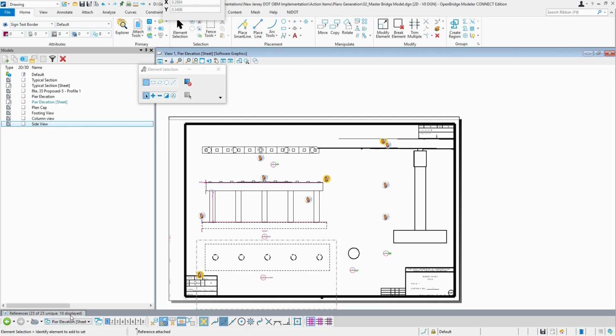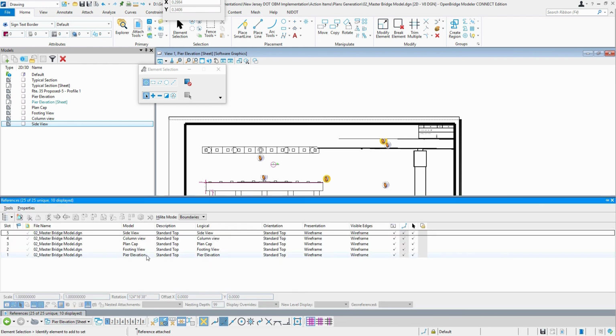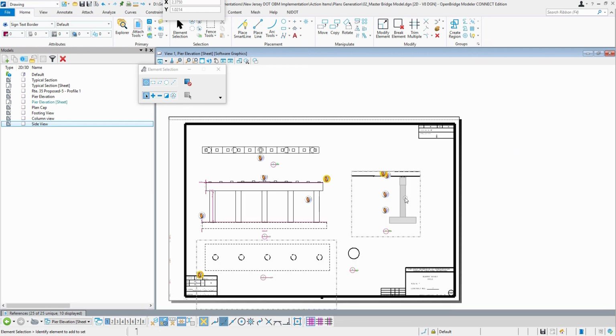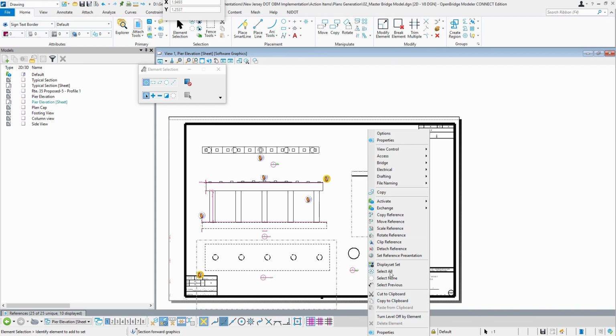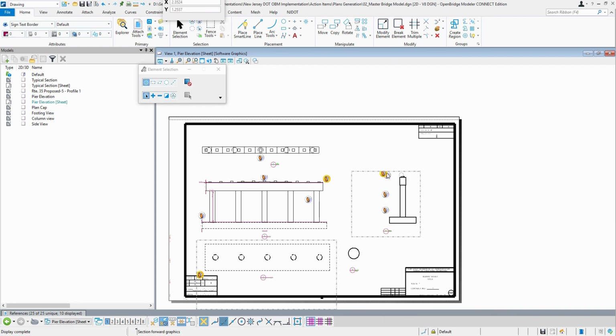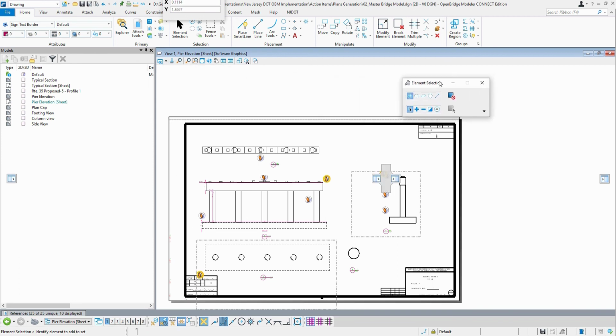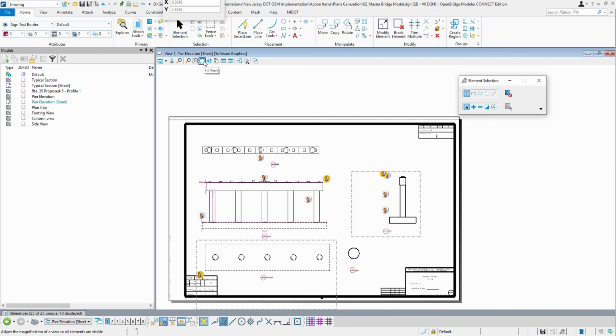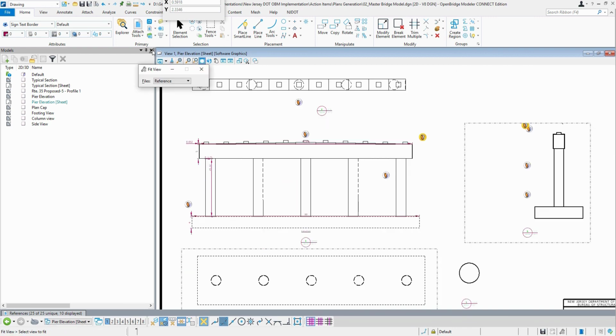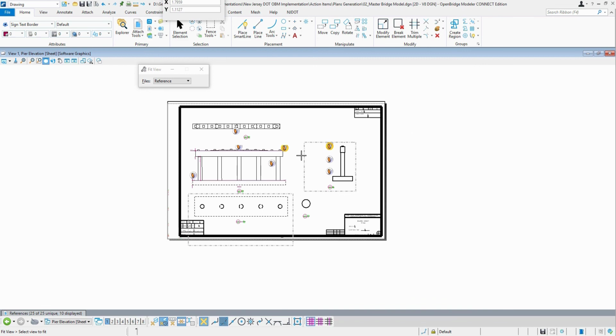So now it will be a matter one more time to adjust the level symbology, to adjust the display rule, clip boundary, move the reference to see where you really want to locate that sheet. Then, after that, what is left is just the text annotations that you want to put in your sheets, certain labeling, and all these different views coming from the 3D model. If the model changes one more time, it will be updated all automatically for you. Then with that, you will just compose your sheet.